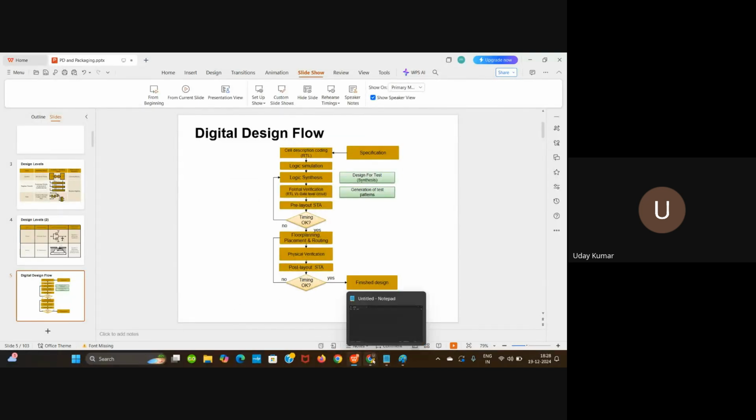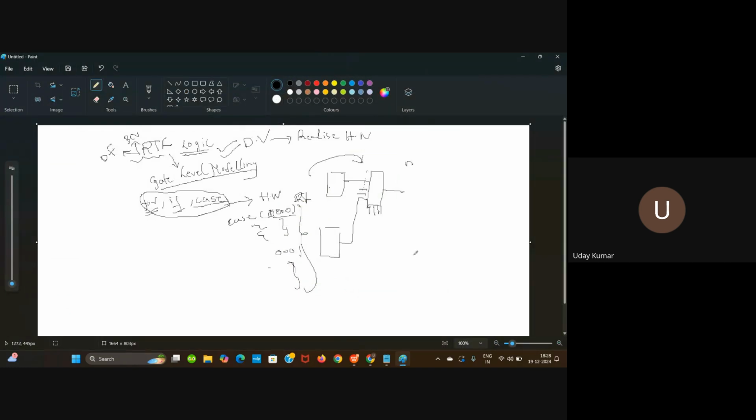So let us say you have long nets, and if you have long nets, there will be long delay. We'll be discussing that. If you have long delay, the tool will try to add some buffers on these nets to reduce the delay, because it is similar to how we have repeaters along transmission lines, electrical lines. We can see that on highways, on the right and left side of the roads. Every 2 kilometers we'll have repeaters so that the voltage level would be amplified to the initial level. So this is also the same.